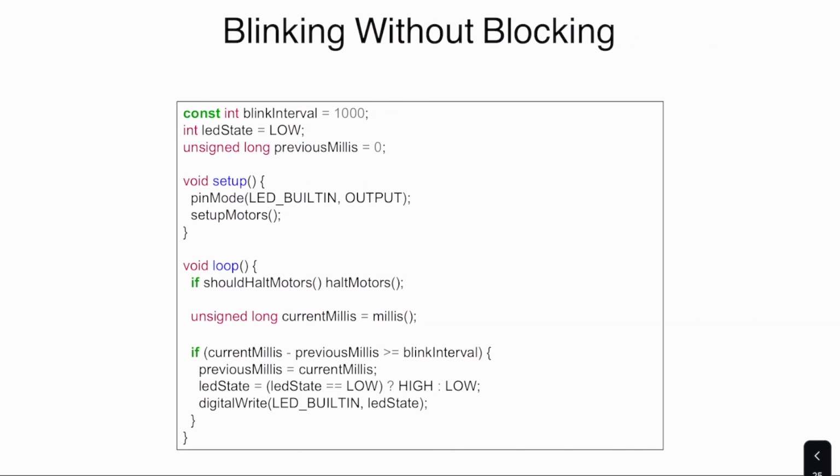So what does that mean if we introduce our motor setup again? Well, this LED blinking, again, only takes as much time as when the if statement is true, having to turn on an LED. If the if statement is false, we just immediately jump down. So the worst case scenario for here is however long it takes to run this set of instructions. So a handful of instructions. So this will make your code much more responsive if you write in this manner.